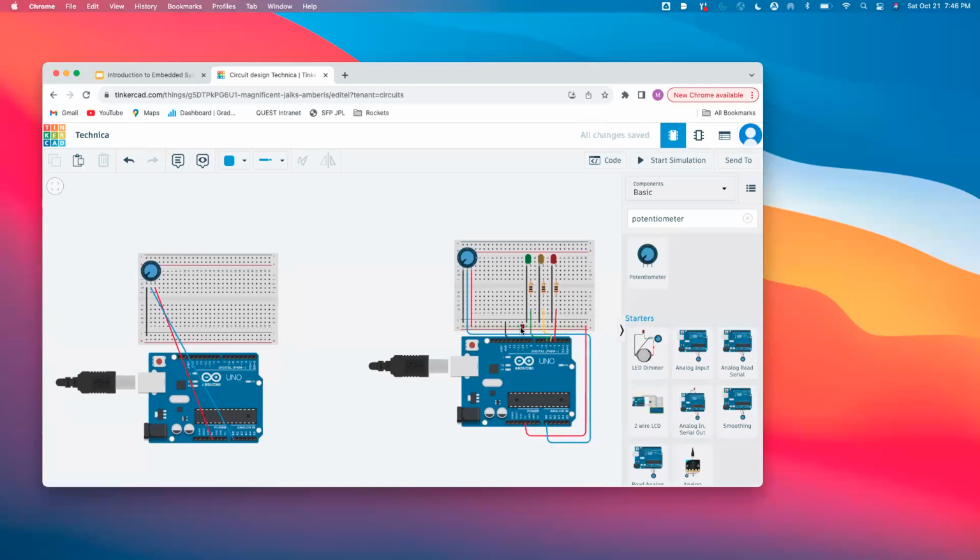The next thing we're going to set up is, let's quick connect the ground between the Arduino and the breadboard. So I think this one's ground right here. Just connect that to the black rail. It's just a thing to make the circuit easier to read. And then we can go grab our LEDs to put on.